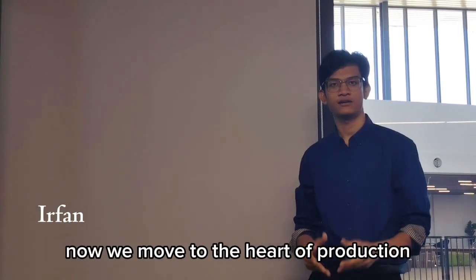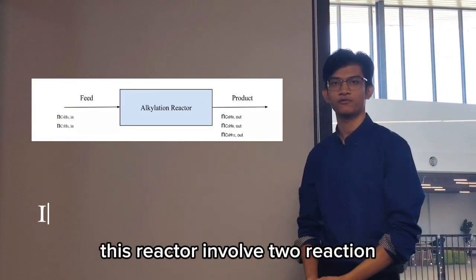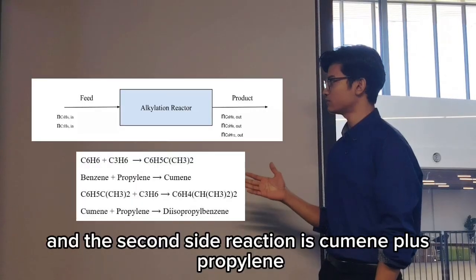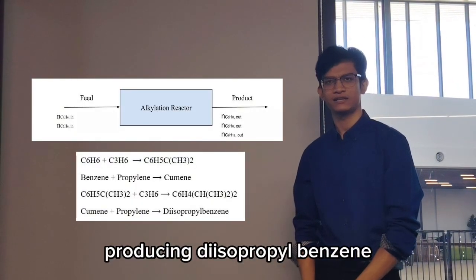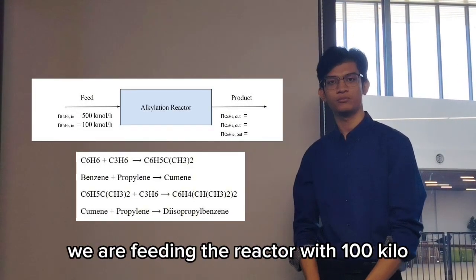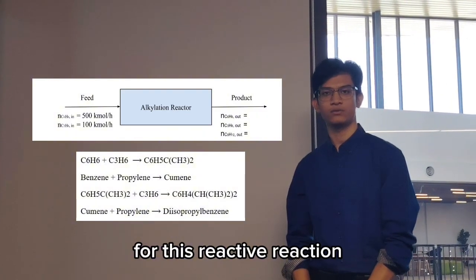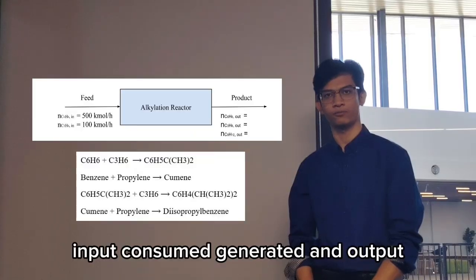Now, we move to the heart of production, which is the alkylation reactor. This reactor involves two reactions. First is the main reaction, benzene plus propylene producing cumene, and the second, a side reaction, is cumene plus propylene producing diisopropyl benzene. In this model, we are feeding the reactor with 100 kmol per hour of propylene and 500 kmol per hour of benzene. For this reactive reaction, we have four parts of calculation: input, consumed, generated, and output.